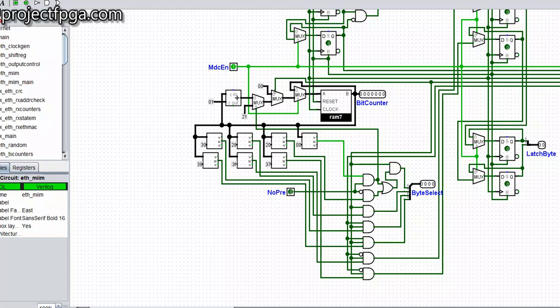See, this is 20. 20 in hexadecimal is 32. Whenever it is equal to 32, it means you are finished counting 32, and that 32 allows the preamble to be counted. That's why you can turn it on. Either there is no preamble or there is a preamble. And this AND gate here makes sure that an operation is in progress before this first byte can be turned on.